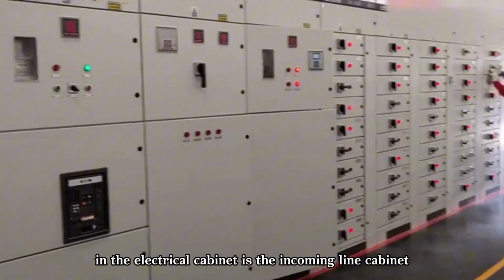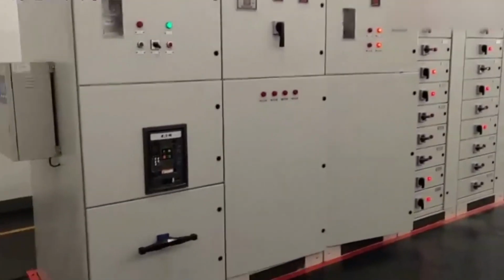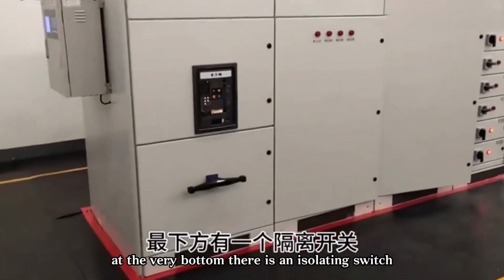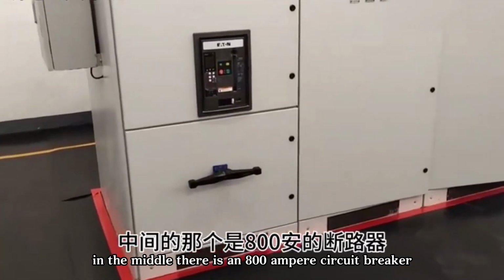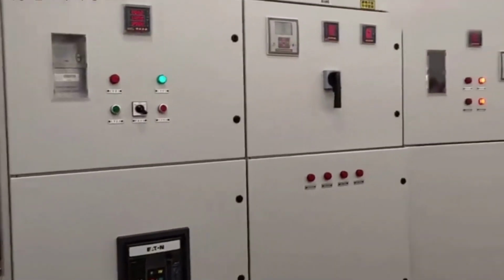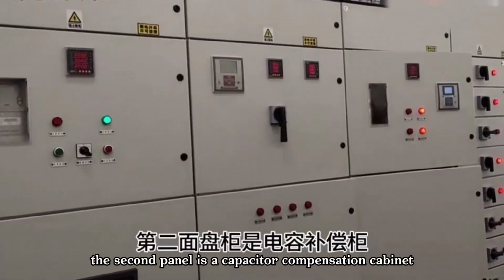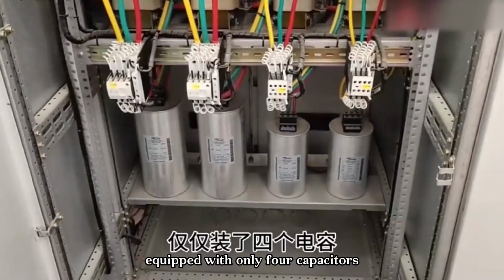The first cabinet in the electrical cabinet is the incoming line cabinet. At the very bottom, there is an isolating switch. In the middle, there is an 800 ampere circuit breaker. The second panel is a capacitor compensation cabinet, equipped with only 4 capacitors. Very simple.